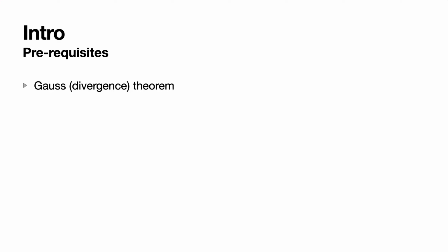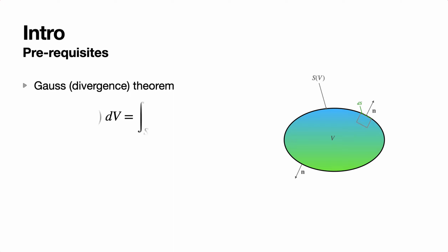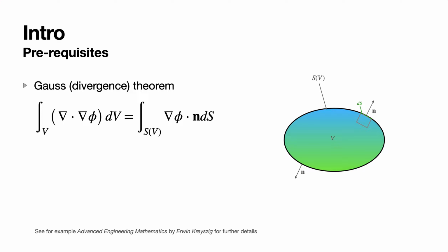Another important thing to recall is the divergence theorem. Given a control volume surrounded by the surface F with a unit normal vector n at the surface, the divergence theorem relates the volume integral of a quantity to the surface integrals. These are also termed as fluxes in CFD because they represent the exchange of a quantity along the boundary. This is very useful for finite volume formulation.